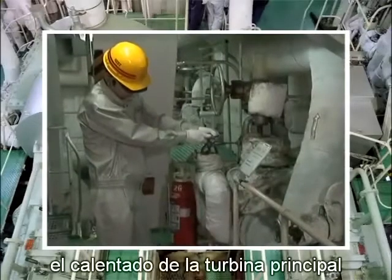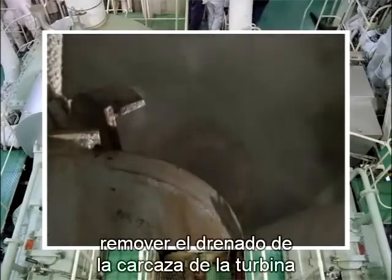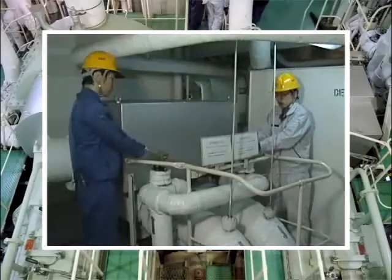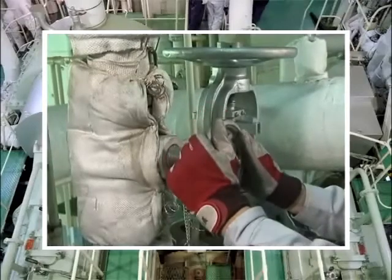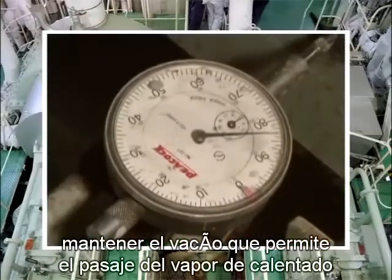Warming of the main engine turbine is accomplished by supplying warming up steam. For steam to pass, it's necessary to remove drain from the turbine casing and keep the pressure inside the main condenser lower than the atmosphere. The following steps are necessary to maintain vacuum that allows the passage of warming up steam.